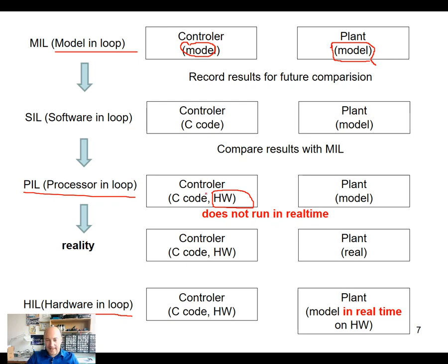Note that this runs on hardware. As we have the hardware controller already, which might be the board, we can connect it to the computer and run it with a plant model that is in simulation. Or we can already connect the plant and run it with the real plant. So here you can see that in reality this is our result.